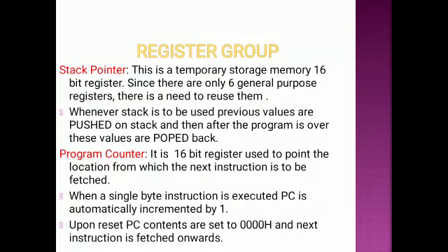When stack is used, previous values are pushed on the stack. Then after the program is over, these values are popped back, and the stack pointer works on the LIFO principle, last in first out. Another is the program counter. It is a 16-bit register used to point to the location from which the next instruction is to be executed.